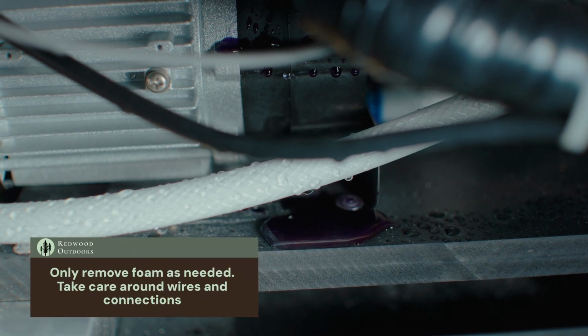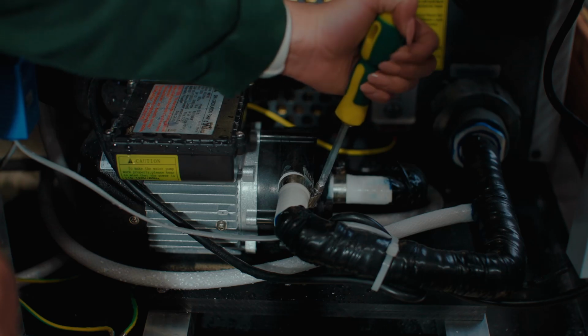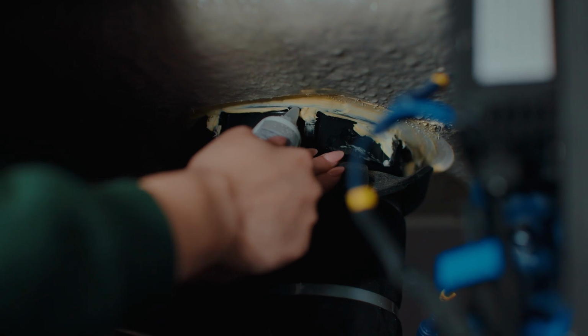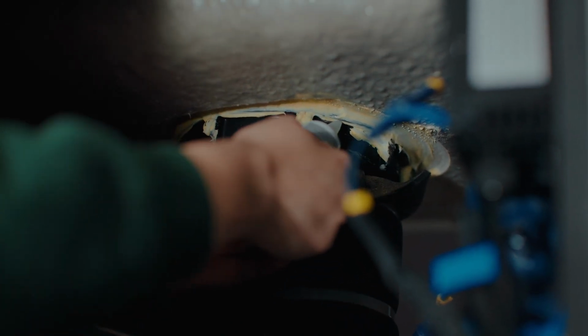Work slowly and remove only enough foam to access and inspect the suspected leak area. Some leaks may be resolved by tightening fittings or resealing the affected area. If the fitting, gasket, or housing is damaged, replacement of the affected component may be required.